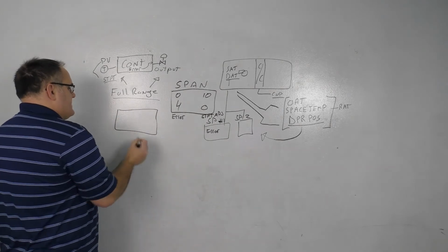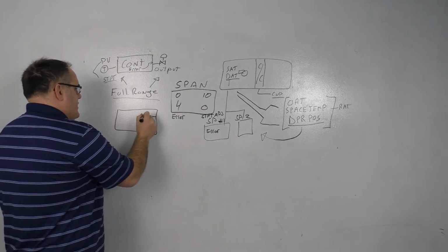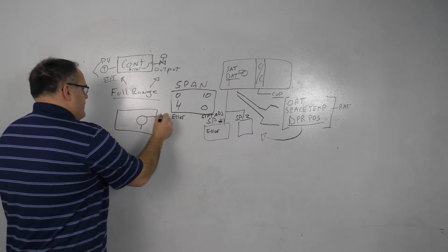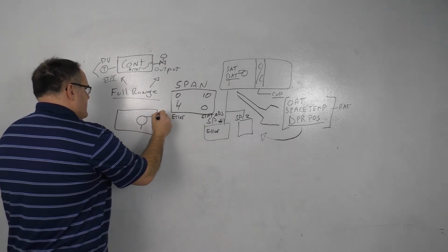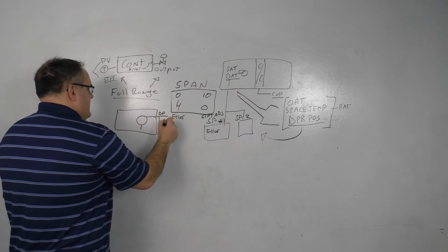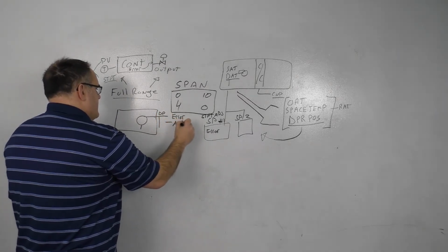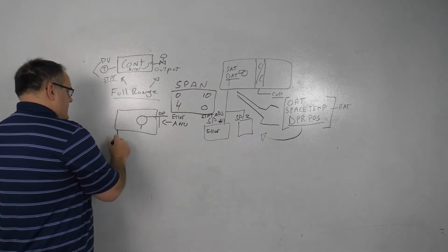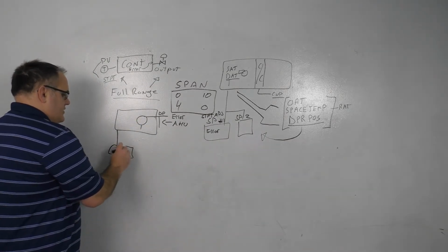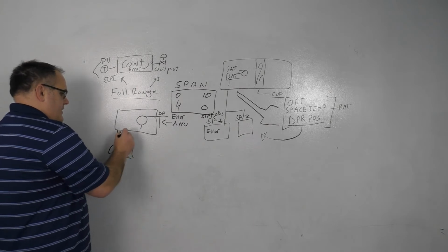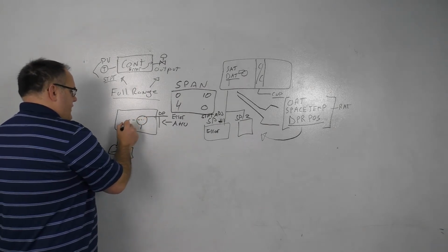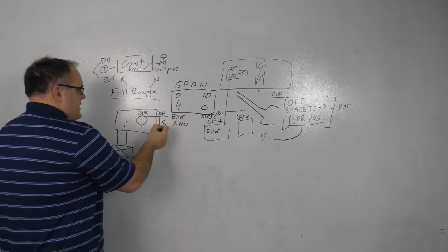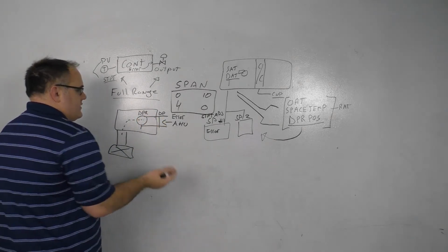So on a box, typically, you've got your air coming in here, you've got your actuator, you've got your flow sensor, so this is your DP, and this is coming from the AHU. Then it goes into the box and then goes out to your diffuser, okay? So you've got your airflow coming through, and this damper opens and closes to control to a certain CFM.